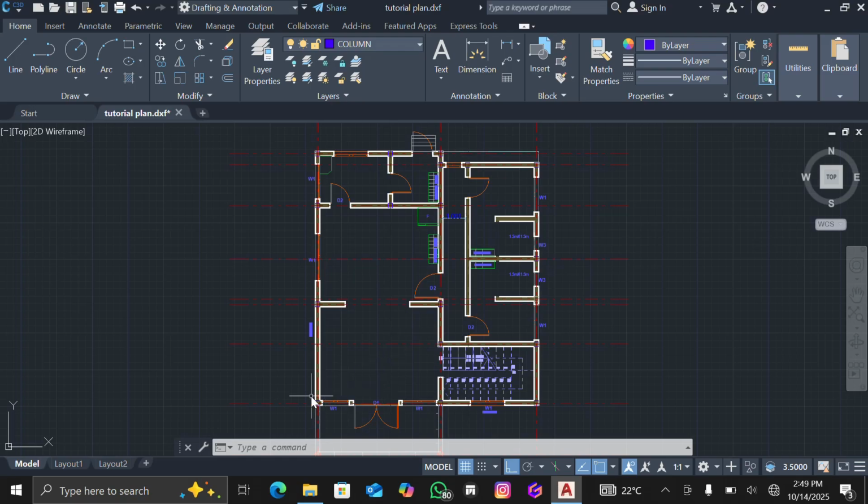So in case you have here, maybe from here up to here, something like 6 meters, and then here up to there something like 5, that is 30. You get it? Because 6 times 5, what do you get? Basically, I think you get 30. So that is still within the range, because the bigger the panel, the weaker. If it's beyond 30, it will bring about vibrations. If the panel is too big, that is one of the reasons why you can receive vibrations.